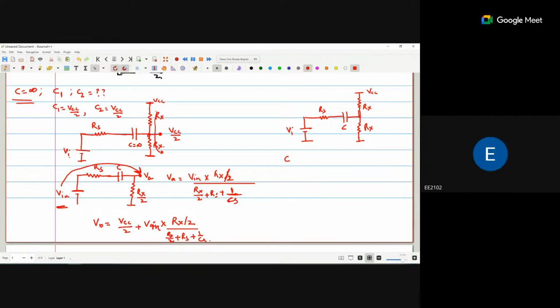Basically, we have to replace all the voltage or current sources with their internal resistance. Generally we say that this is idle, so no resistance, short. This VCC will be the ground. Now with respect to this C, this R. After this R, it is grounded. Ground will be connected at these two points, and after that it goes to C.